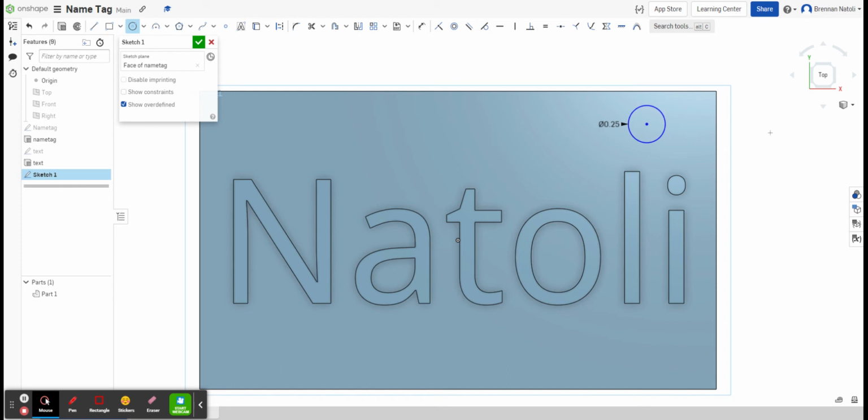Now you can dimension this in place. So I can break this command and move this to where I want it. You do not want it really close to the edge because it'll break. I would say you can eyeball it, but I would dimension it. By dimensioning it, I can use the dimension key and click the center of the circle and the top of your piece.